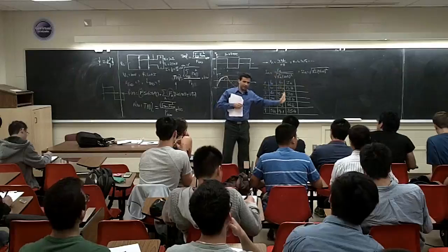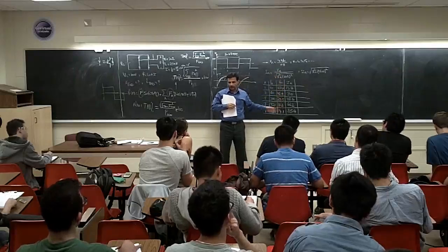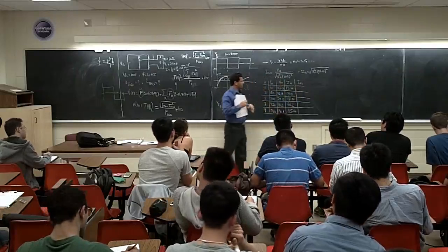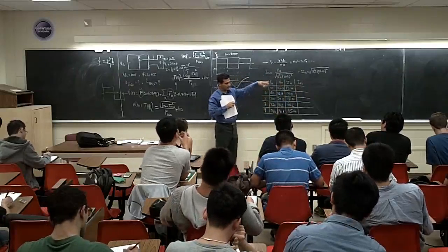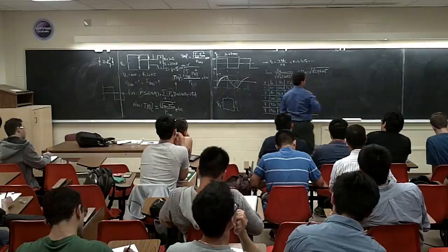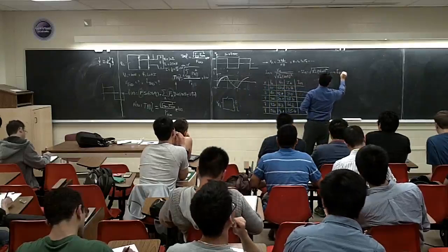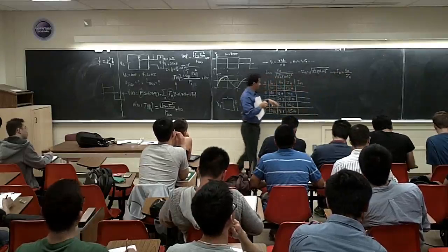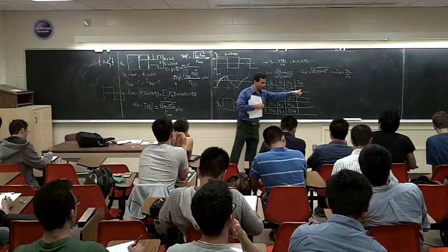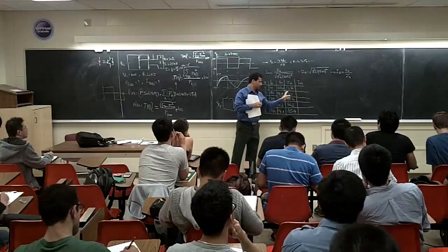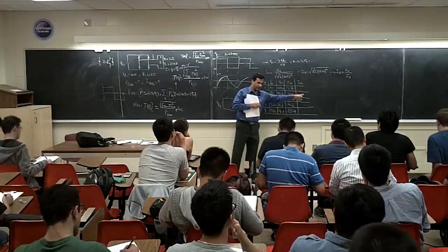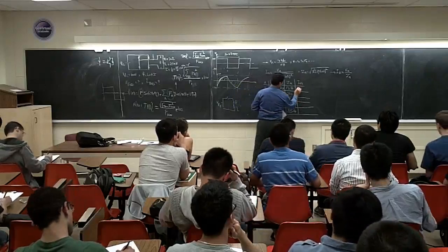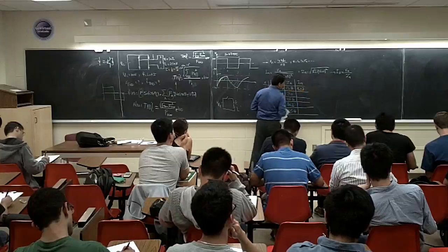So we calculated the harmonics of the voltage. We calculated the impedance for each harmonic. Now I can calculate my current harmonics, right? How much is In? Vn over Zn, right? If you look at these two equations, basically In is Vn over Zn. So we'll go V1 divided by this one is I1. V3 divided by Z3 is I3, right? Let's calculate those ones. So if you go here, it's going to be 9.27 amps.